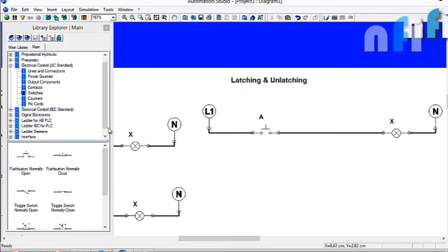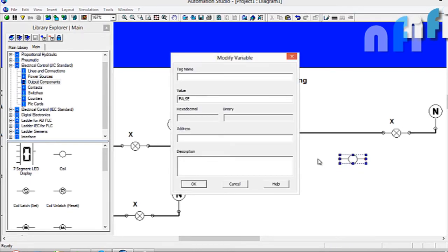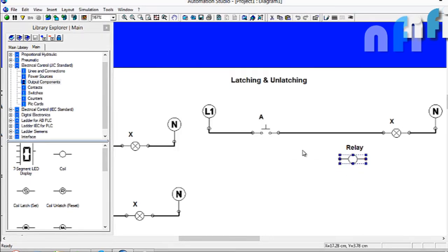To make that we need an additional component which is called a relay. A relay is an electromechanical switch in which we have a coil. This is a coil, and we have some contacts. Let me tell you what this coil and contact are. Initially, a coil is basically a wire wound in a round shape. If you provide a signal to this coil, it will become an electromagnet. It will start having a magnetic action. Due to that magnetic action, it will attract and repel a contact.